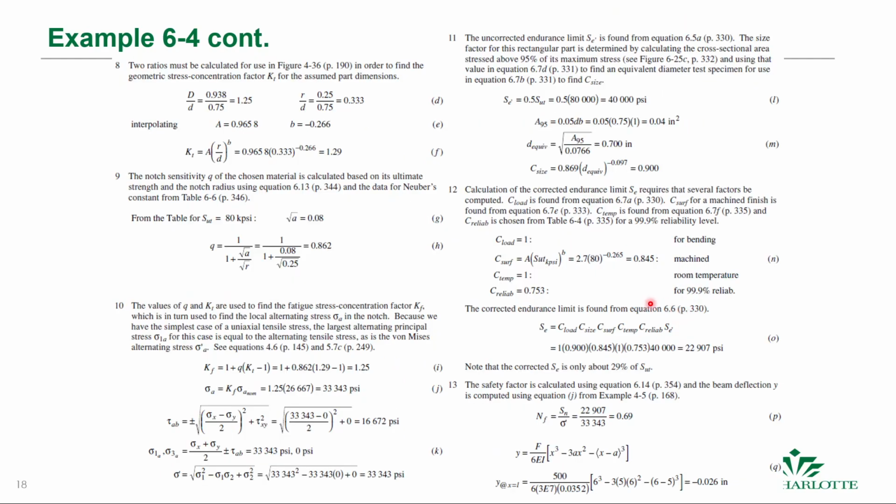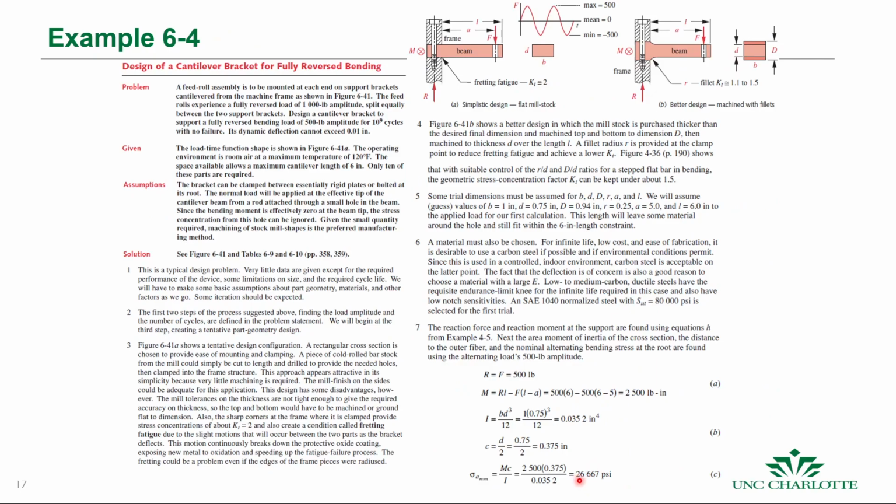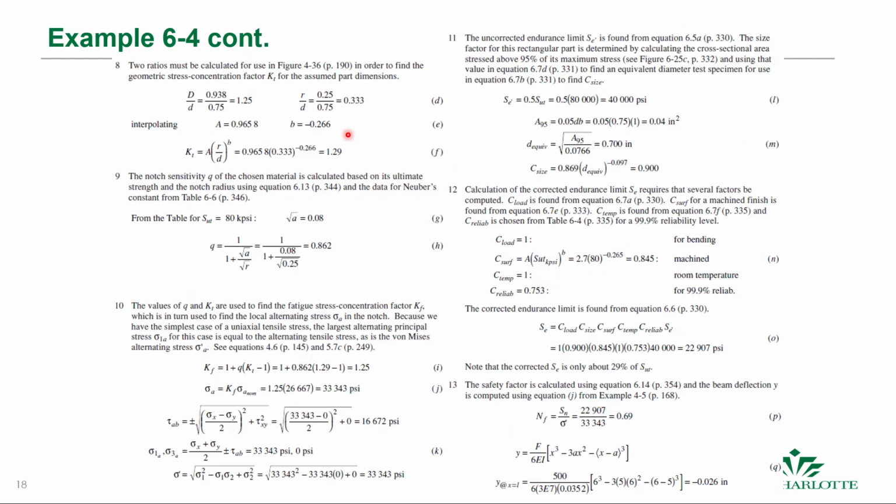Okay, so then what we need to do is calculate those ratios for the stress concentration factors, so we can go to the graph for that loading condition and get our stress concentration. And we can already tell that with this value and this value, we may be a little bit too close to the yield stress for that material. But let's go through the process anyway.